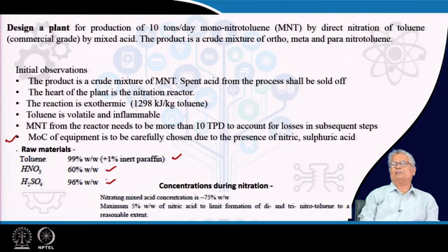A maximum of 5% weight by weight of nitric acid is to be the limit of nitric acid concentration in the reactor, and this would limit the formation of di and trinitrotoluene, which are not desirable products. Some amount of formation is inevitable, but a practical limit can be set by limiting the nitric acid concentration during nitration to 5%.